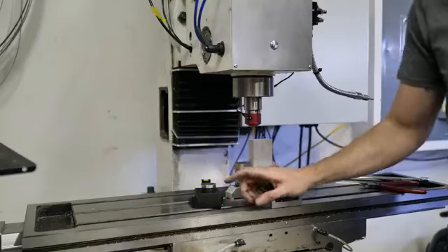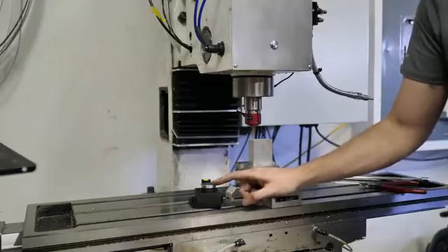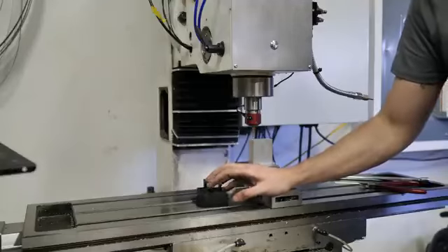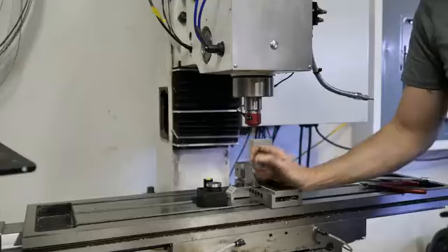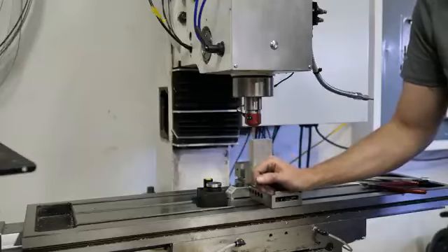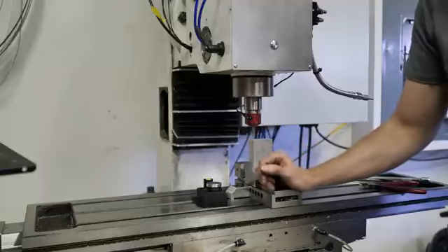All right, the final thing I want to talk about here is these tool height offsets. Again, I don't think most people that are using Mach 3 are using height offsets, at least not in the way that I've been trained to use them, or the way we figured out how to use them in the Tormach world, you know, with PathPilot.